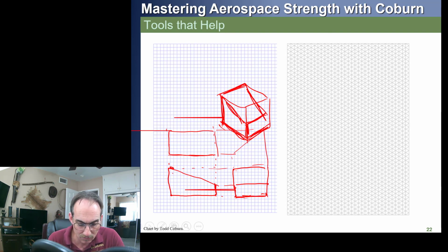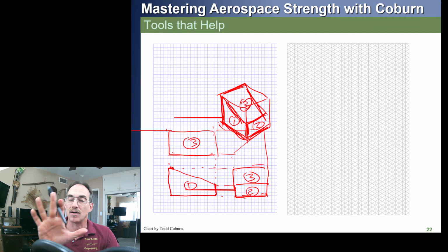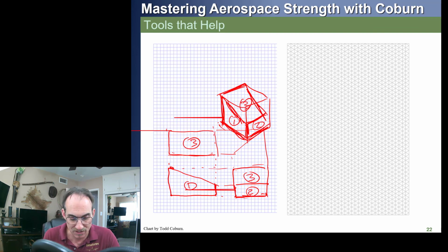When we're all done, we're going to have three faces. You'll notice this front face is this face here. This face here is this face here. This canted face is actually this and this. Now you can't measure on those because it's oblique, it's not flat. You can only measure on surfaces that are parallel to the plane that we're viewing. Anyway, that's how it works.